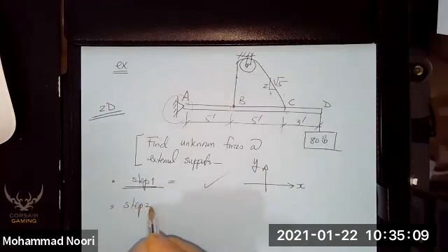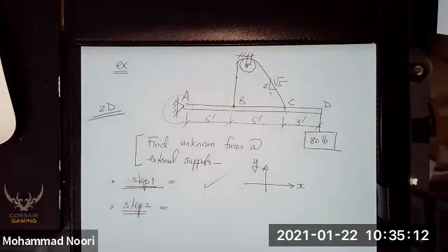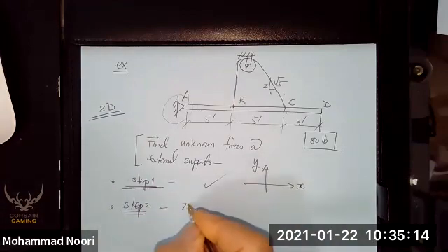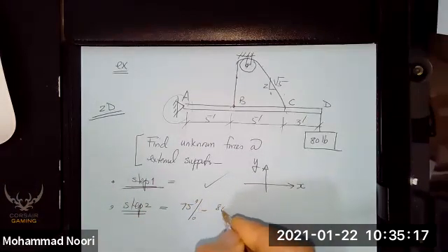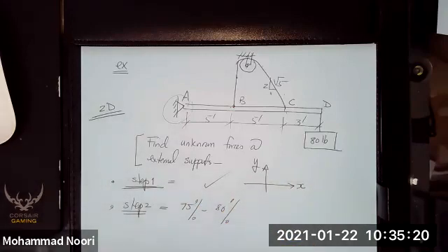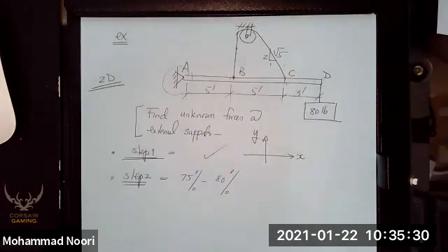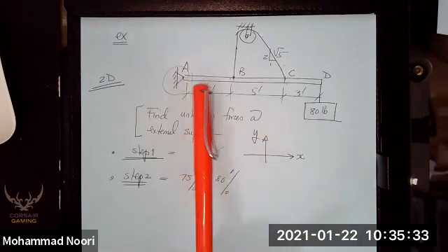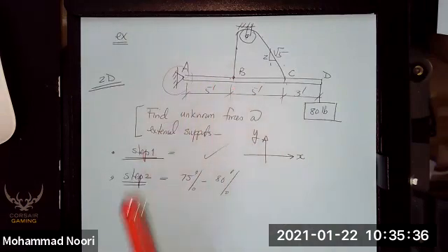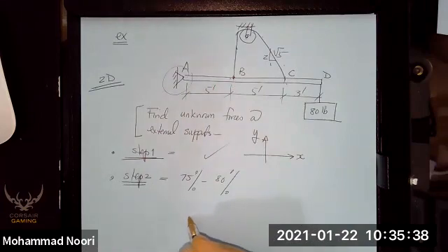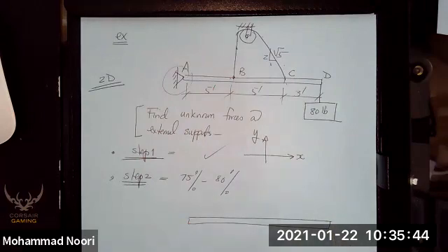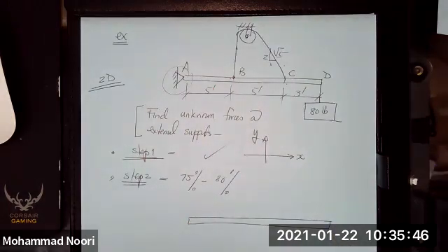Step two is really the heart of statics. I would say that is 75 or 80% of solving static problems. And what is that? This is what this step is. You look at the object that you have, okay? You cut that object from everything that is supporting the structure and the load that is acting on that.